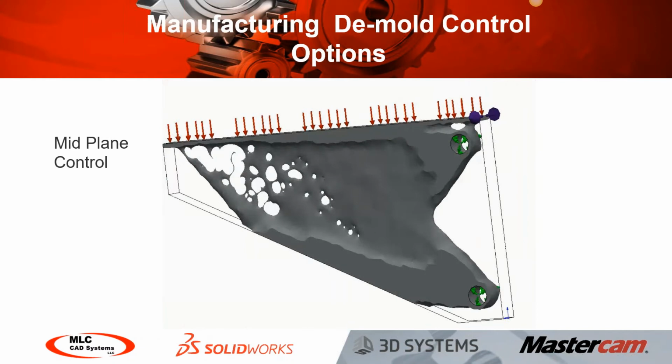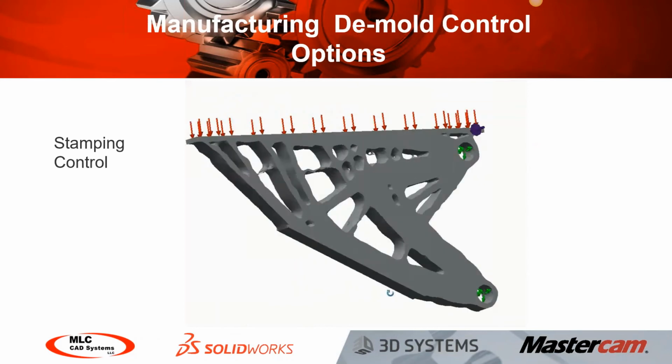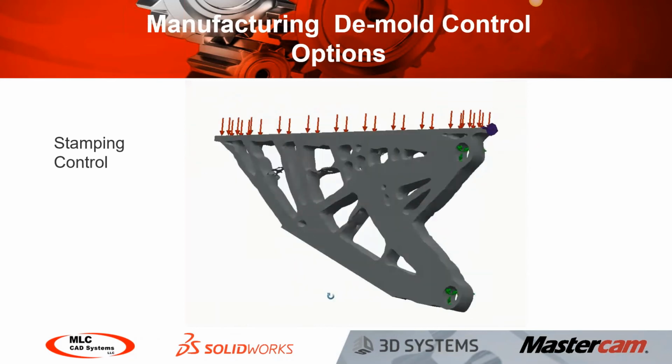If we apply a stamping control, we get this part here. It basically has through holes in it. Material is being removed in the direction that we specify all the way through. So we could produce this part using a stamping process, or maybe a machining process where we could machine all from one side of the part. So that's a stamping control.